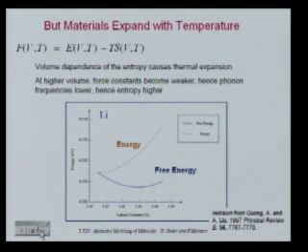Okay. So if you want to do the full solution, you would go and look at the thermal expansion to predict the lattice parameter. Well, how do you do thermal expansion? Remember where thermal expansion comes from. Thermal expansion comes from essentially the volume dependence of the free energy. And that comes from two terms. You have an energy that's volume dependent, and you have an entropy that's volume dependent.